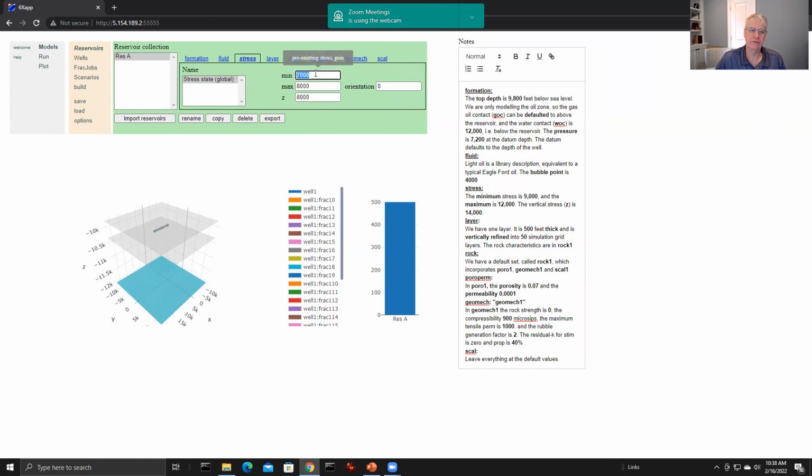And we're going to plug in those stresses that we talked about. The data can be rotated so that it's not all perpendicular and parallel to each other. So if the well was not drilled along the stress direction, you could specify that here. We're going to stick with 0 for all our orientations so that everything stays perpendicular, parallel, square with each other.